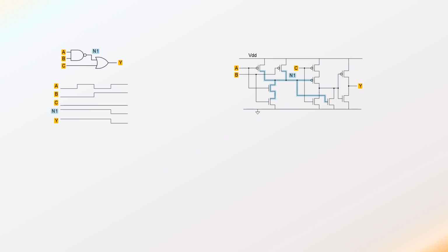Focusing a bit more on that node N1, on the right in the FET diagram, I added a single capacitor. I'm going to look at all of those conductors highlighted in blue as collected into one single capacitance. And that's a fair thing to do for a basic analysis because all of those conductive elements are connected and they're all separate from ground. And so there will be capacitance between all of that highlighted node and ground.